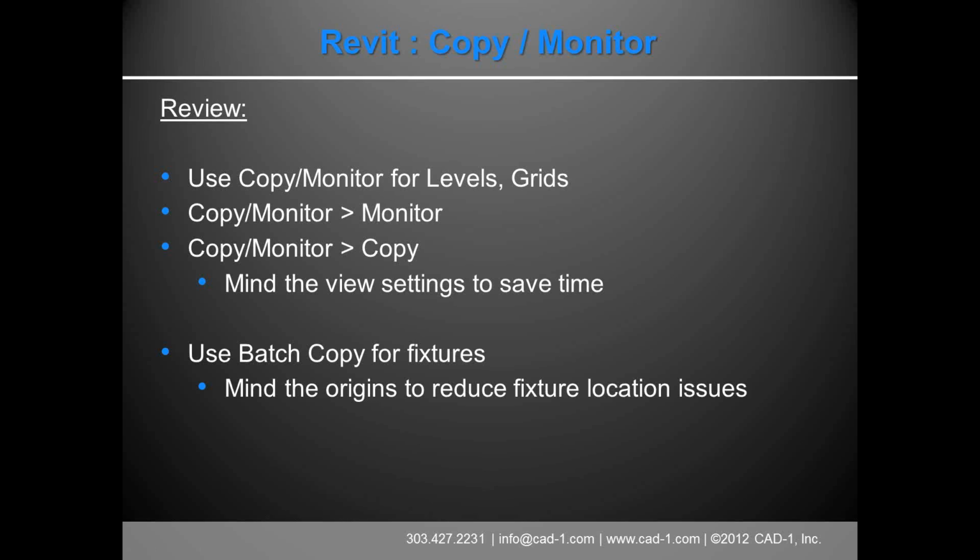And you can look at more efficiency. I can't think of the word I'm looking for. Some tools in the view settings that can save you some time. When you create a level, Revit creates views. When Revit creates the views, it assigns the view templates, and within the view templates are a lot of settings. So just by doing a couple of steps, you can have Revit do many steps for you, and it really increases the efficiency if you have it set up ahead of time.